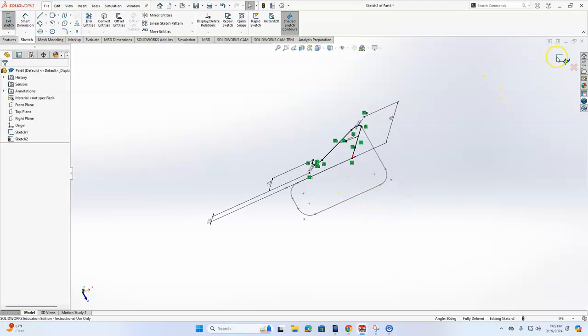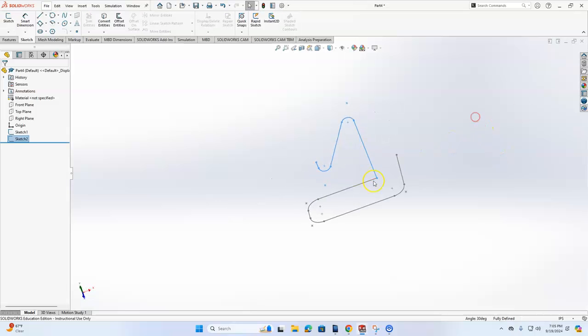Now I'm going to close this sketch. Now I have two separate sketches here. I need to convert them into one uniform 3D sketch, and I will need to make some fillet here because we can't do this bend. It will mathematically be impossible as a sweep path.